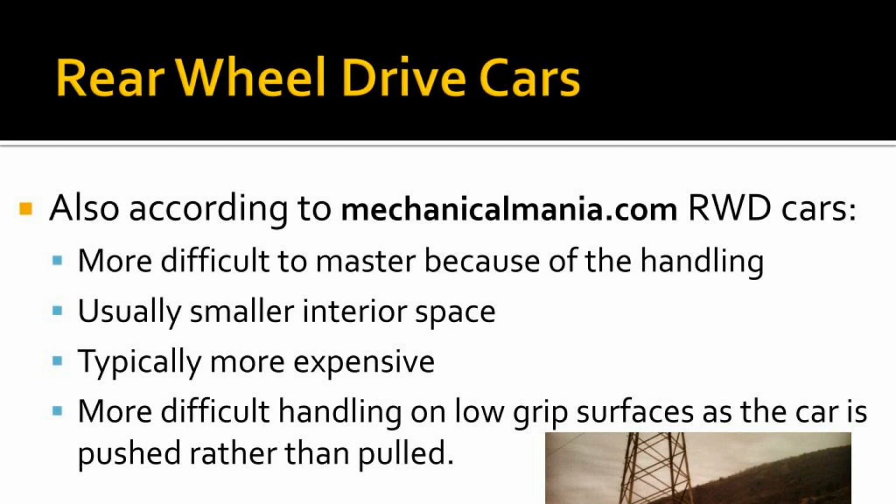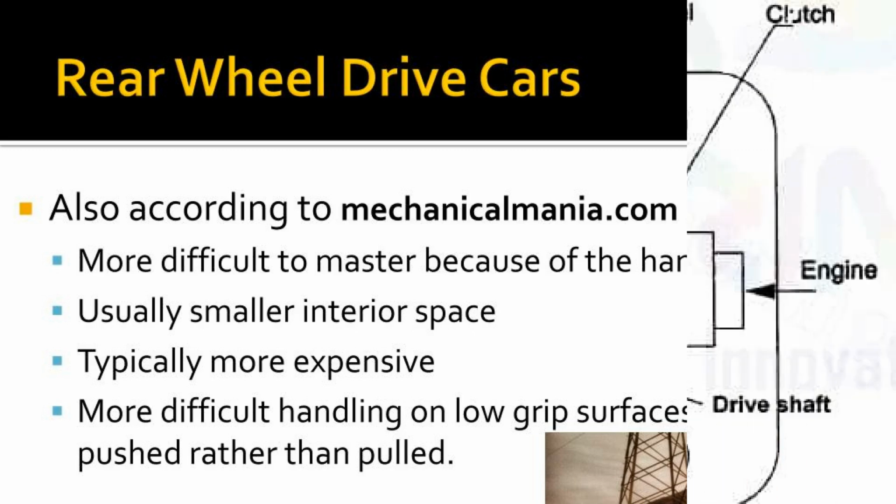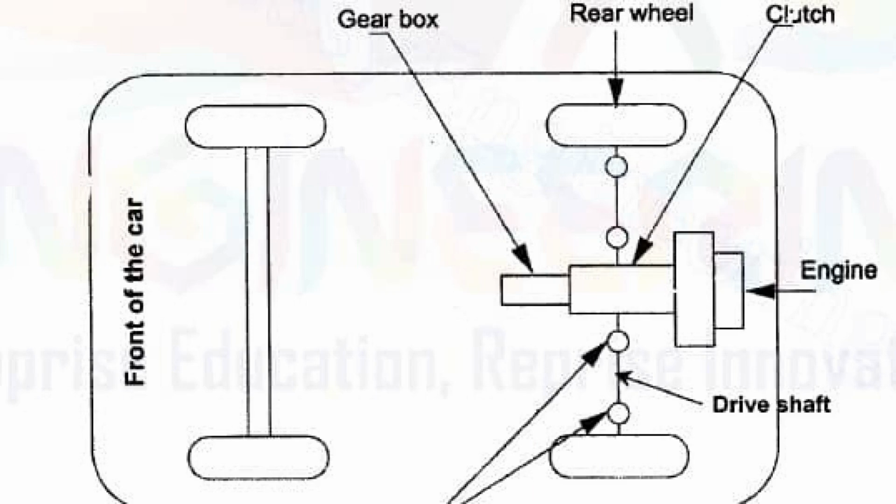More dynamic acceleration on surfaces with a good grip coefficient. During acceleration, the vehicle squats, thus transferring the load to the rear axle. A rear-wheel drive car gets more traction on the drive axle. In a front-wheel drive car, the drive axle is unloaded during hard acceleration, which reduces the traction coefficient of the wheels. Note that this principle does not work in conditions of slippery surfaces.